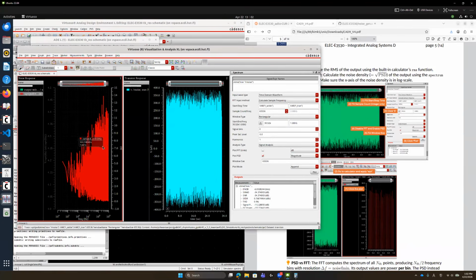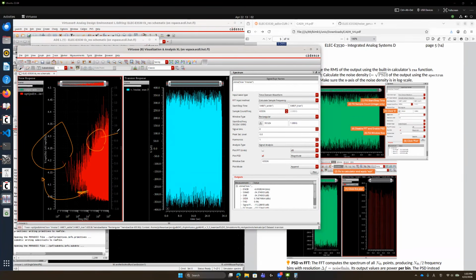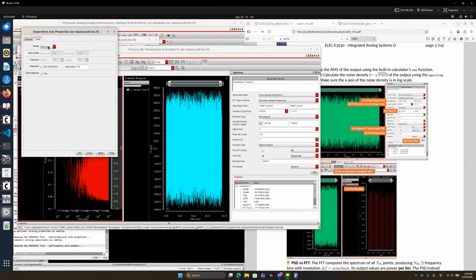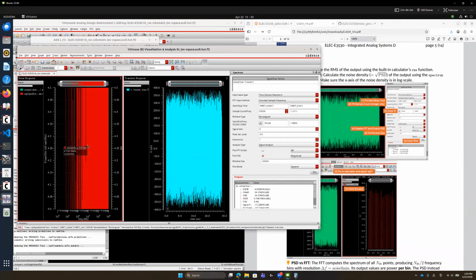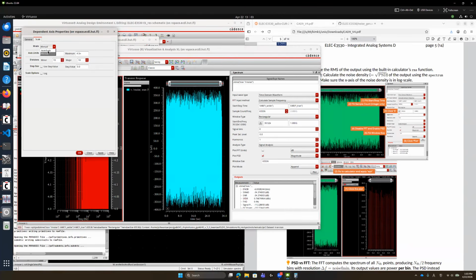Yeah, then you can see that, by the way, the y-axis is different. Even if we are plotting here, the y-axis for our resistor noise is here. Our green curve is here, and our red curve for power spectral density is on the right side here. So the unit is different. So in this case, it's better to match the unit with, for example, 4 nanovolt to 4.5. So if I set 4 nano, 4.5 nano, then you can see that it is fluctuating a lot, even if it cannot fit into our window, right? So let me go back to auto scale.